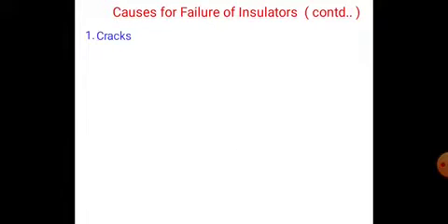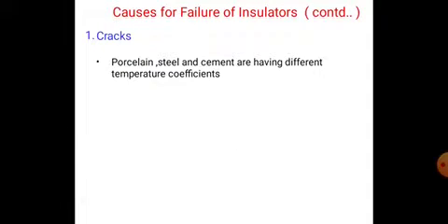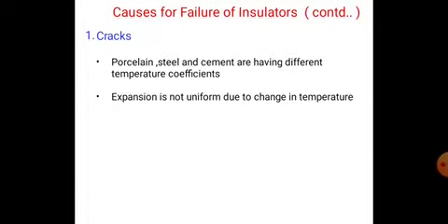And short circuit. Cracks occur because porcelain, steel and cement have different temperature coefficients. So expansion is not uniform due to change in temperature.